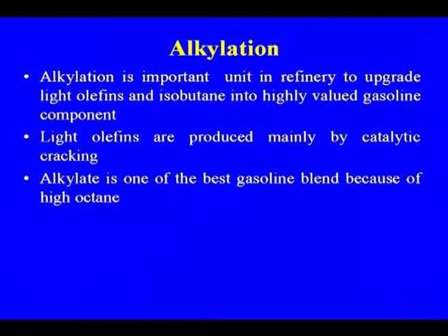Now there has been a lot of emphasis in refineries to separate the various useful components of C4. C3 propylene we are already recovering, but now there is continuous interest in recovering the C4 components of FCC gases. Alkylate is one of the best gasoline blends because of its high octane number.